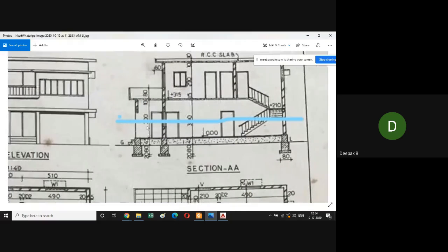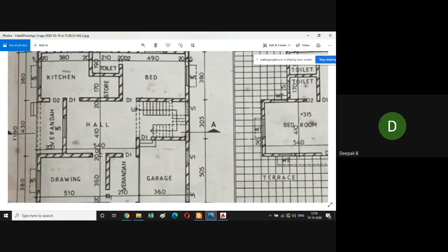Okay, so this is the cutting section for the floor plan. As you can see, there are a few steps from the first flight. Then the entire second flight and third flight is actually above this line, so it is not actually visible when we are looking down. But in order to show that there is a stair there in that particular floor, we are using dotted lines.